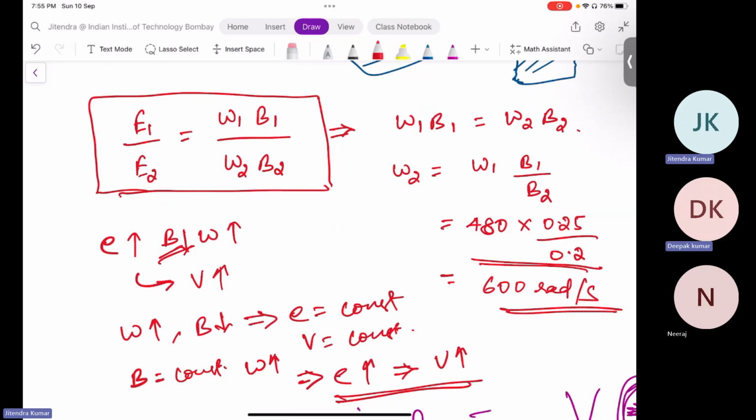And you are reducing this flux to increase the speed range. So this is called field weakening operation, because you are weakening the field and increasing the speed. Now you can guess where it is applied. Very, very popular and emerging thing in India also. Electric vehicle.